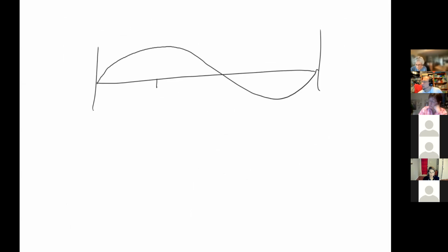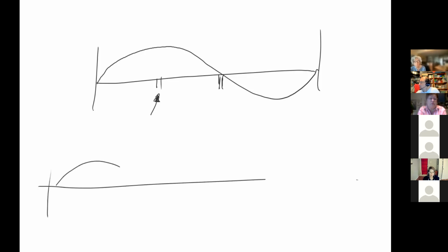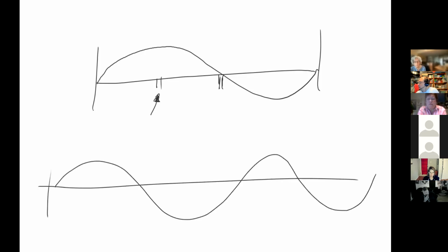well, honestly, you'd basically probably want to feed it off center, which you can. If you feed it in the center, you're feeding it at a very high impedance point, so it's hard to put power into. A half wave antenna is typically going to get you the nicest pattern. You can actually make an antenna that looks like this, multiple wavelengths long.